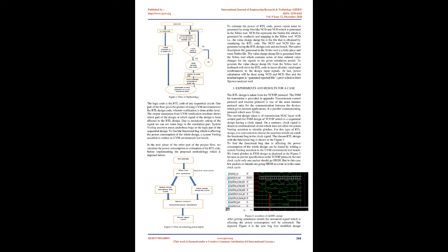2. Project flow. The project flow as depicted below describes the inputs from logic code, which refers to the RTL design code and its test bench. The logic code is the RTL code of any sequential circuit. One part of the flow gives the picture of applying the UVM environment to the RTL design code, wherein verification is done at this level. The output simulation from UVM verification shows which part of the design or which signal of the design has been affected in the RTL design.